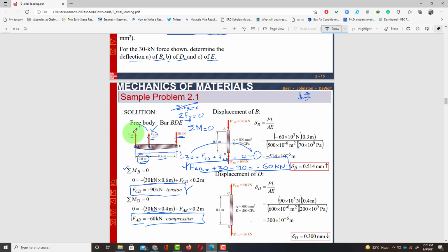So we have assumed here the force upward, so it means that our assumption that we have taken this force upward is wrong, so it should be toward downward. Clear? Yes, sir. Okay, then we will move to find the strain in each bar.